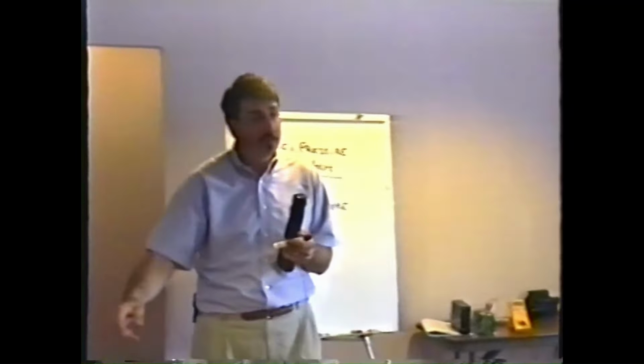And so that's the earth ground. And of course it's 0 volts. In fact, the long slot is also 0 volts. It's called the neutral, N-E-U-T-R-A-L. It's called the neutral side. That's also 0 volts. Theoretically, I should be able to stand with wet feet on wet concrete and stick my tongue in that long slot and not get a shock off of it.